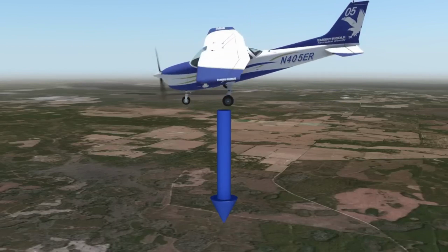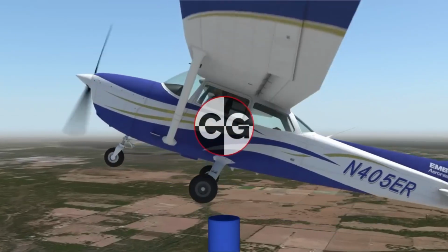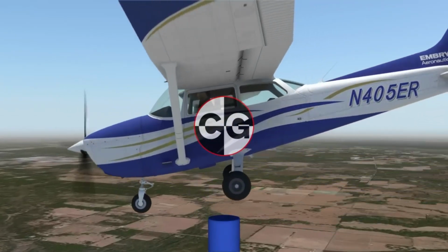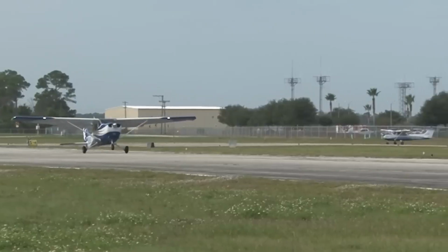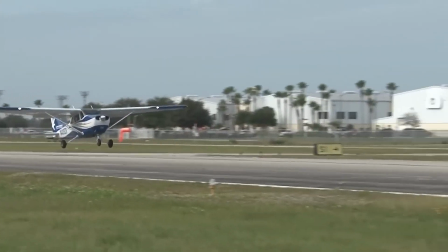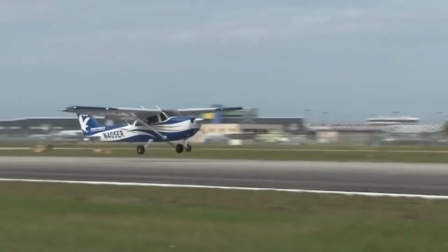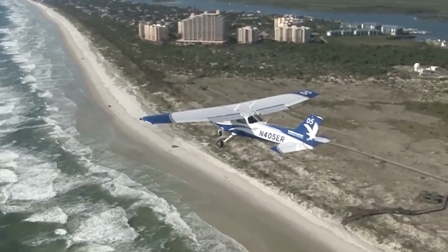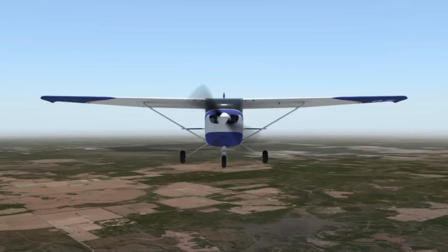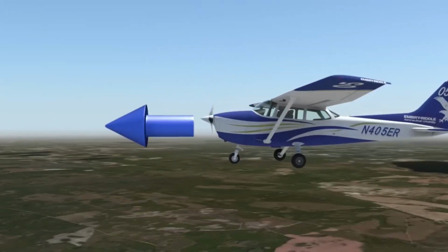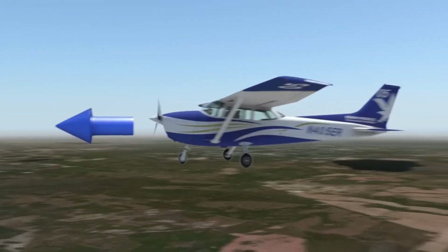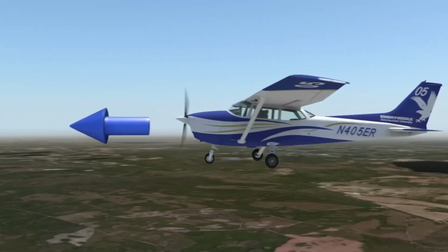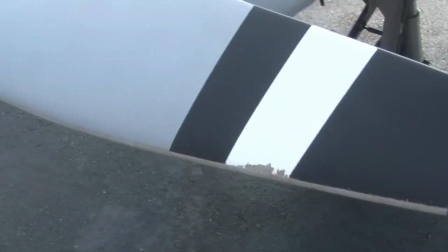Air density is a result of the relationship between temperature and pressure. Air density is inversely related to temperature and directly related to pressure. For a constant pressure to be maintained as temperature increases, density must decrease, and vice versa. For a constant temperature to be maintained as pressure increases, density must increase, and vice versa. These relationships provide a basis for understanding instrument indications and aircraft performance.